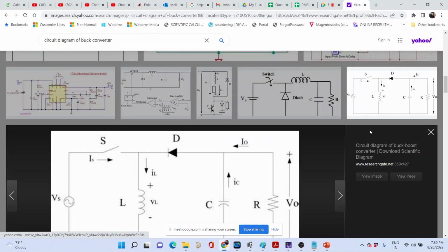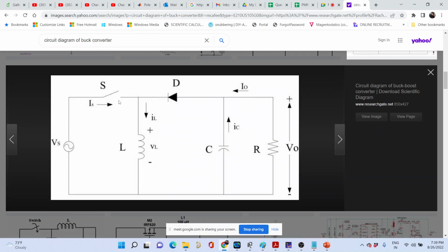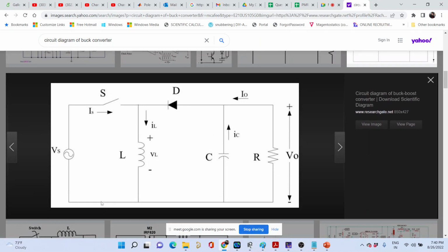Let us just look at this picture. So instead of putting the switch over here, I am putting it on the negative rail. The same switch, I am shorting this path and putting the switch over here. Are you getting it or not? So will there be any difference? No, sir. But it is solving a very critical problem. Do you understand what problem it is solving? Floating voltage.